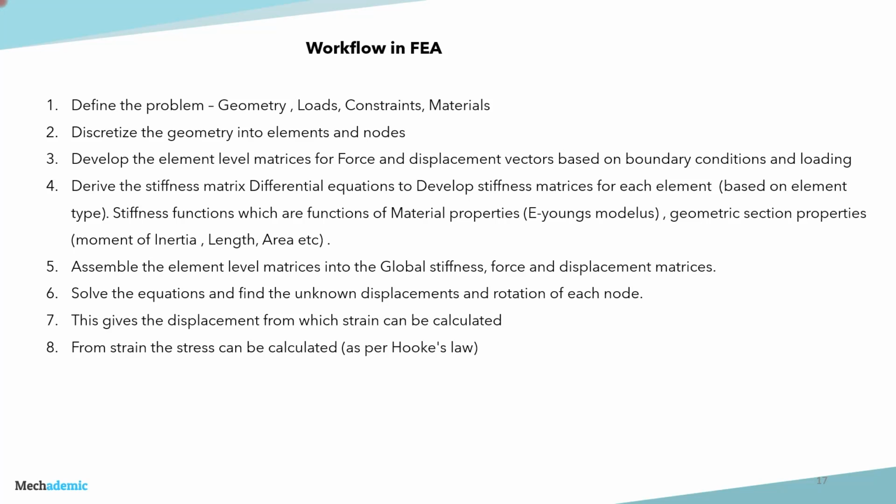Now, after finding out the unknown displacements and rotations for each node, these displacements will give us the value of strain in the 7th step. So the displacements which we find out will give the value of strain, and from the value of strain, the stress can be calculated as per Hooke's law, considering that the material is linear in fashion and follows the Young's modulus. So this is a very basic overview of the methodology of finite element analysis.